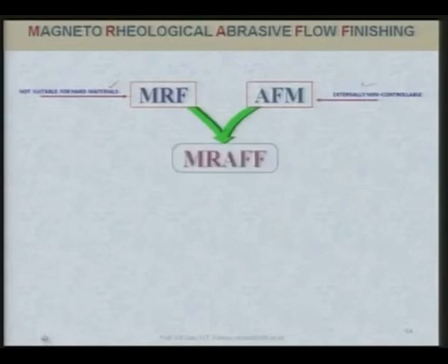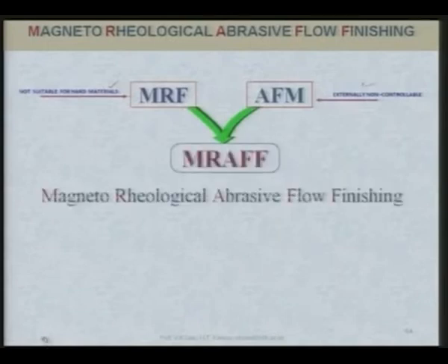MRF is not suitable for hard materials, AFM is externally non controllable. We combined these two and developed the process as magnetorheological abrasive flow finishing.